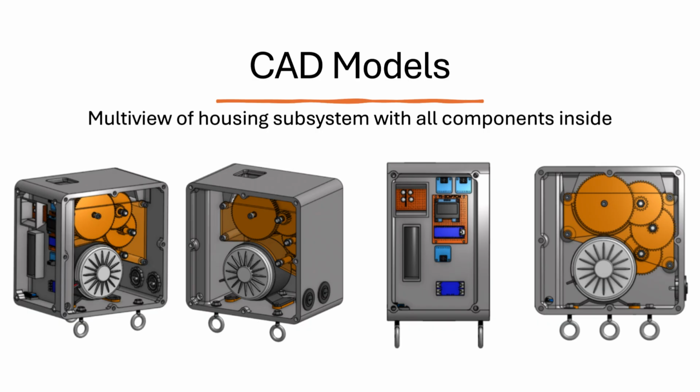from reaching electrical components when exposed to natural elements like rain or even water sprays. So to do this, we did a water spray at angles of 60 degrees from vertical, giving an IP rating of 3, and also needed to test withstanding vertical falling rainwater, giving an IP rating of 1.